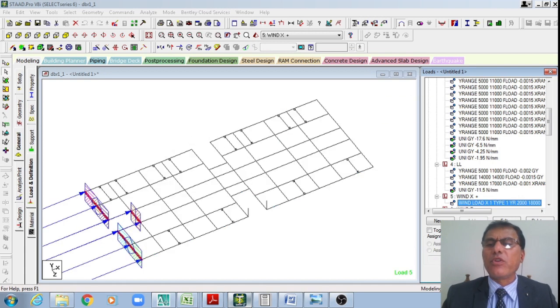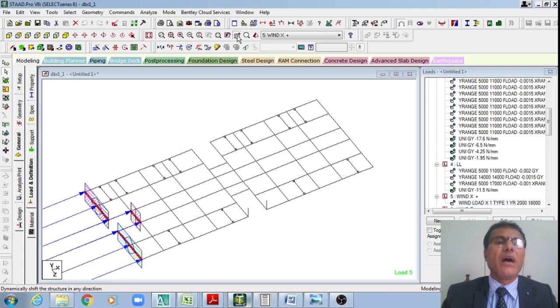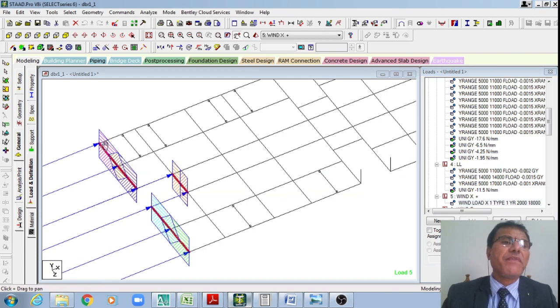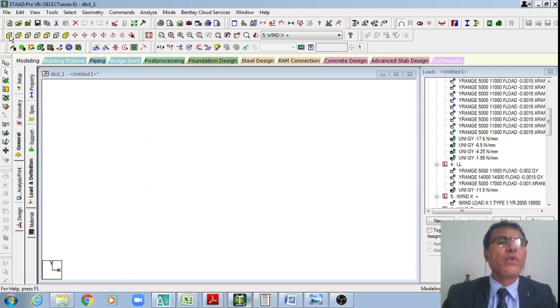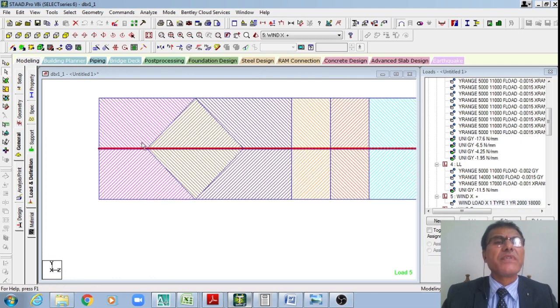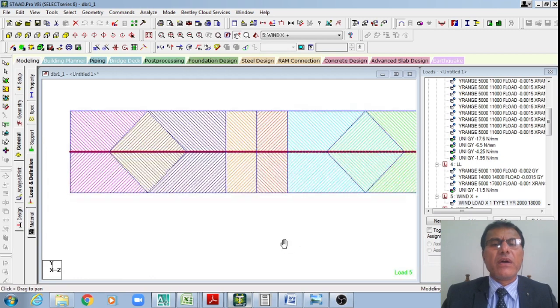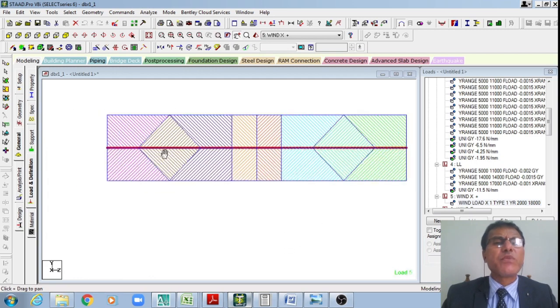If wind is acting, you please see, for understanding it is so easy actually, right? The panel width is half of the height of this floor to half of the height of this floor, right? Therefore if I see this side view, student, there is this exposed area, right?